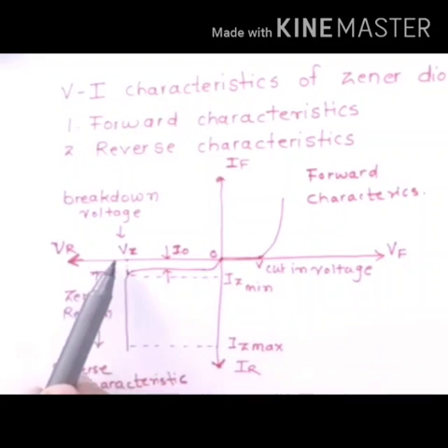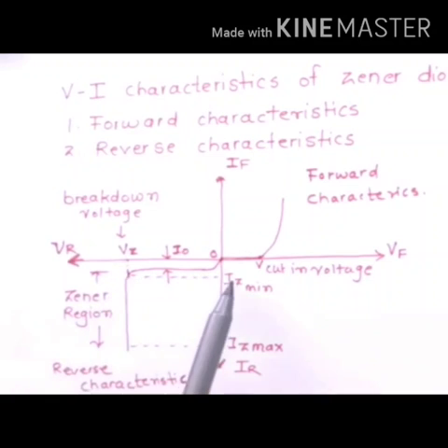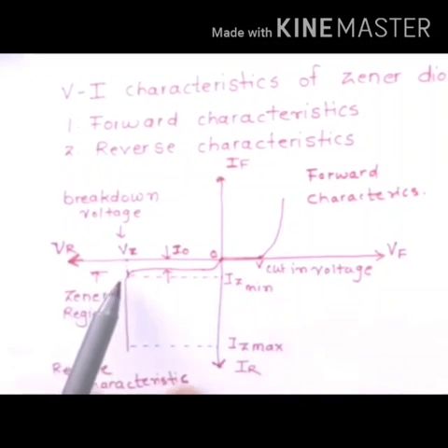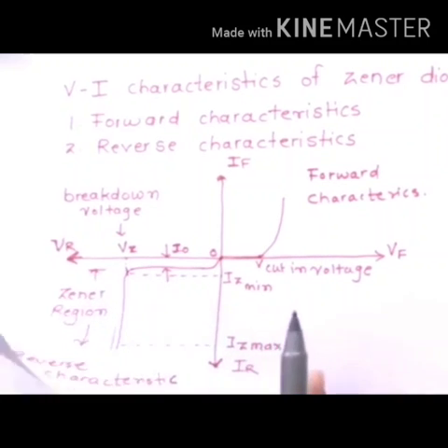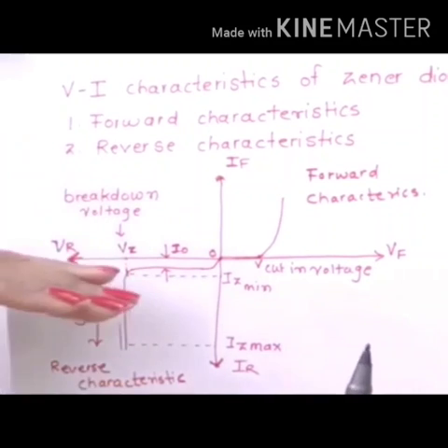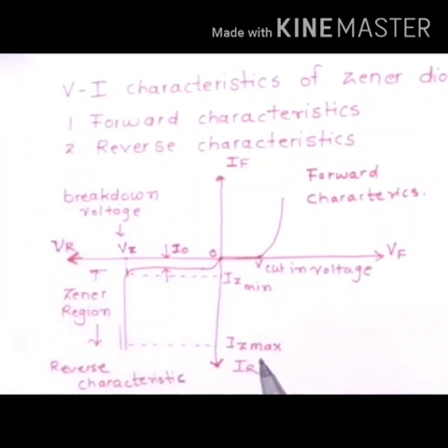It is the inverse of the slope in the breakdown region. It means an increase in the Zener current produces only a very small increase in the reverse voltage, so this can be neglected. The voltage of an ideal Zener diode does not change once it goes into breakdown. It means that VZ remains almost constant while IZ increases considerably.